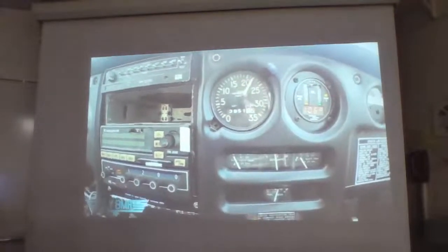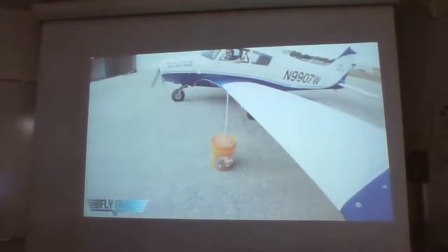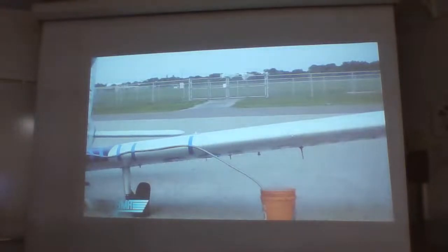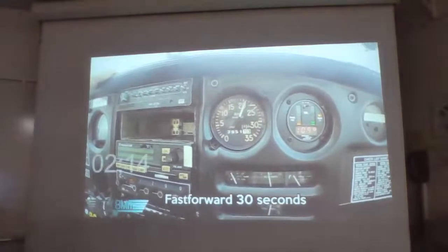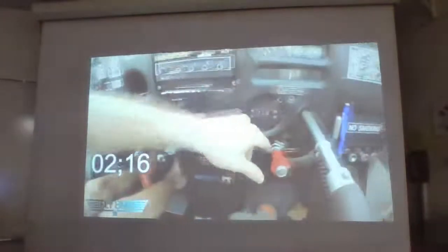we see in flight. Now, what's interesting is the bucket of oil out there is actually starting to smoke quite substantially, meaning the last little bit of oil that's coming out of here is a lot hotter than 108. I've never seen oil smoking. It's actually coming out of this vinyl tube here, just really starting to smoke. Now, some RPM falling off here, 2,100 RPM. It's come down from about 2,200. Still set to full power, still set full rich.